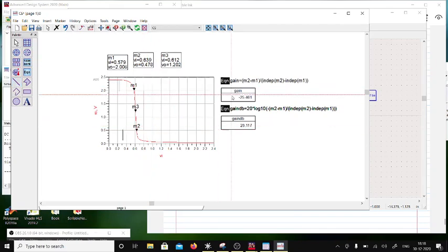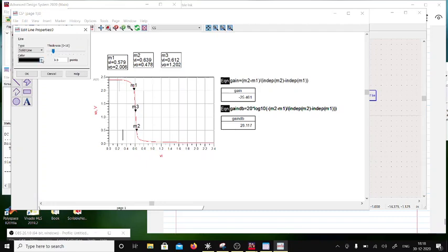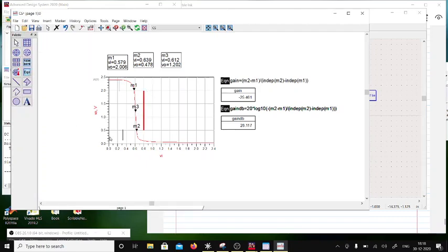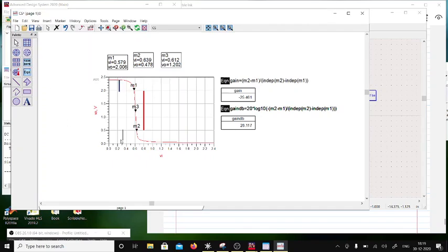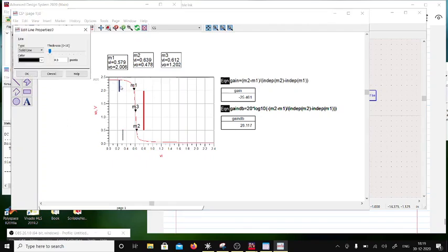Okay, so let me just tell you what's happening here. This is the net swing, and this one is V overdrive. So at the top you lost V overdrive because that voltage would cause the PMOS device to go into triode region.